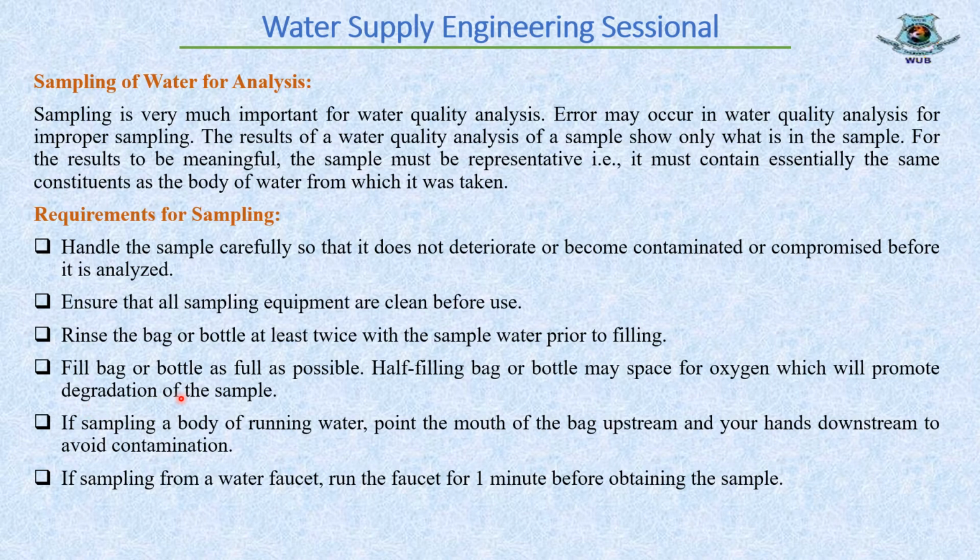Fill the bag or bottle as full as possible. A half-filled bag or bottle may have space for oxygen, which will promote degradation of the sample. As in a half-filled bottle, the half space will be covered by air, and the oxygen present in the air can deteriorate the result.